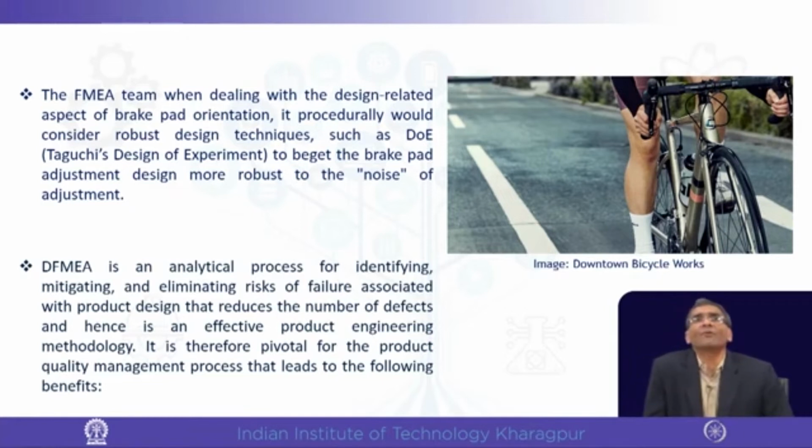The FMEA team, when dealing with the design related aspects of brake pad orientation, would procedurally consider robust design techniques such as DOE, Taguchi's DOE, to make the brake pad adjustment design more robust to noise factors. Noise means, for example, the condition of rain where it becomes slippery, yet it should have a firm grip.